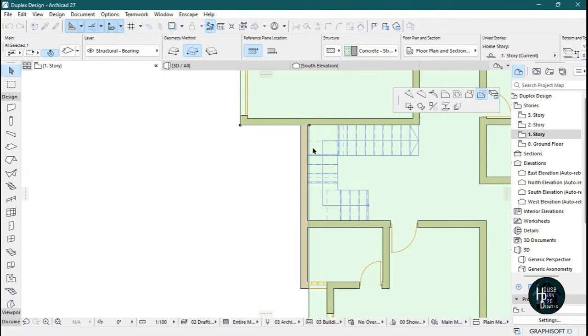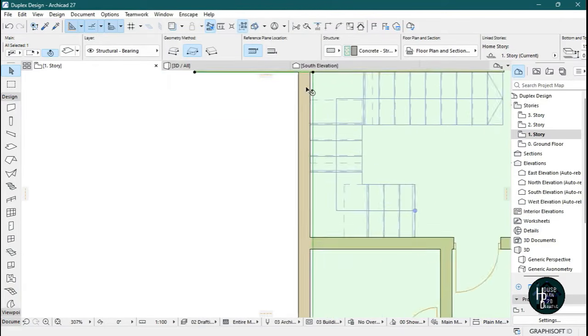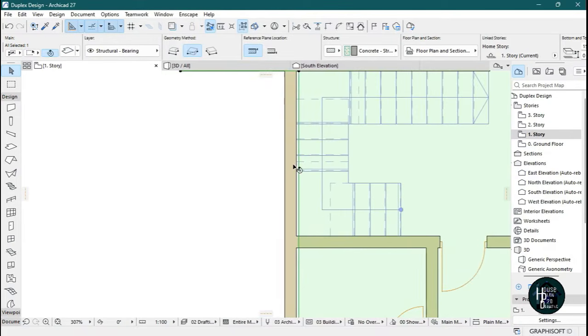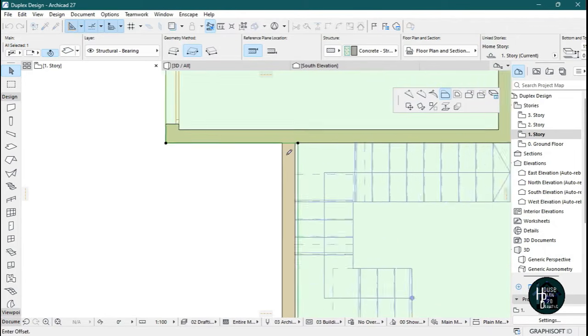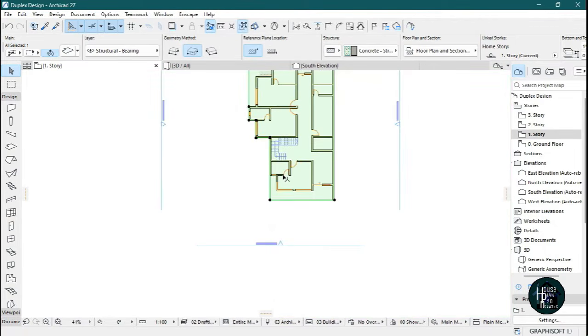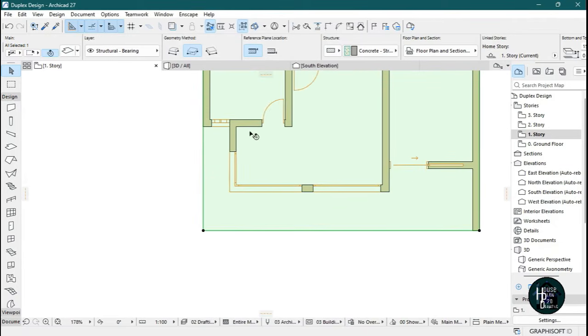Okay, so this particular side I'm clicking right now is not the black node. I'm just clicking this edge. Okay, so I'm just going to click on the edge here. This box is going to pop up, and I want you to come and select this offset edge, and let's move it to the side here like this. So when we've done that, also I want you to come and cut out this part away.